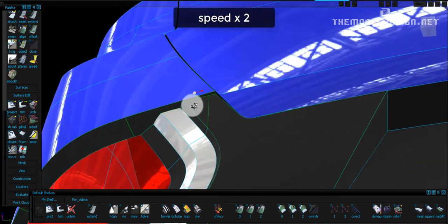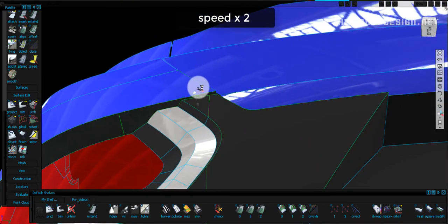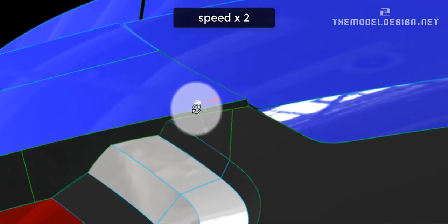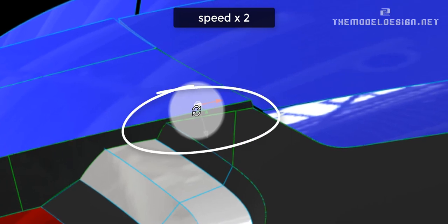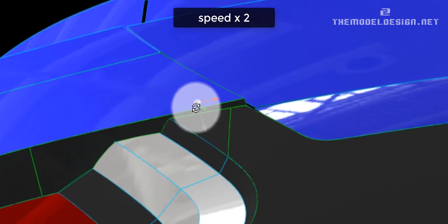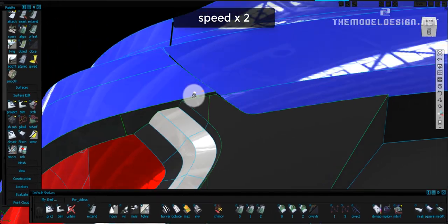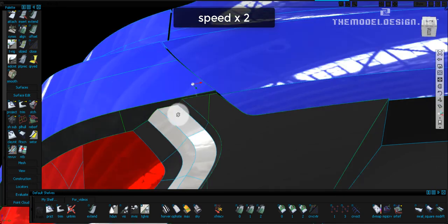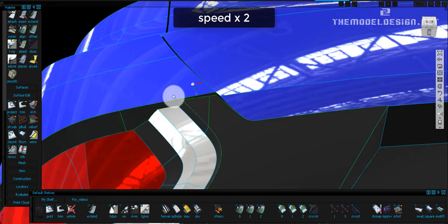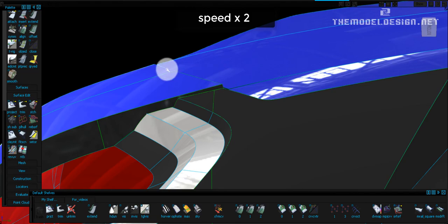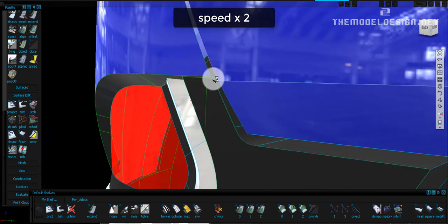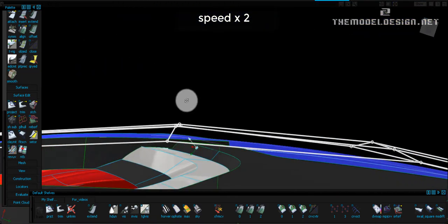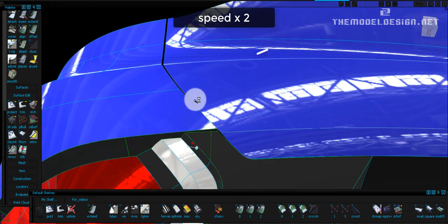There is an issue in here. It is not something serious, but I think it is worth mentioning. If you watched my previous video rear bumper 2, you will know that I decided to remove the additional surface in here. And now I feel like I should have kept it. That little portion was an elongation of the tailgate, and the tailgate is actually very consistent and could be used to anchor our blend corner in here.